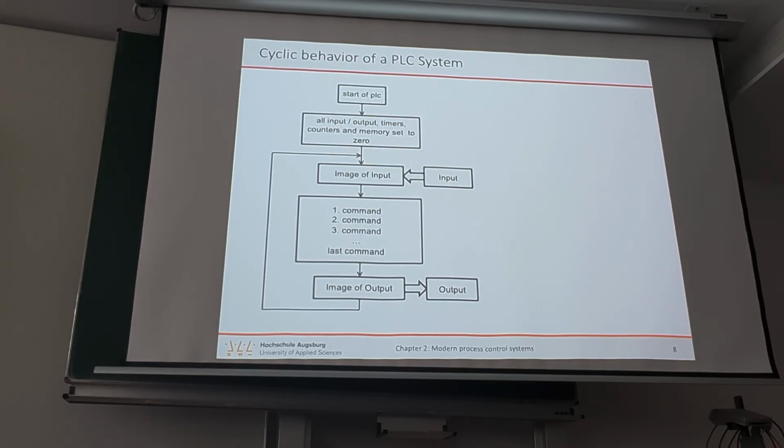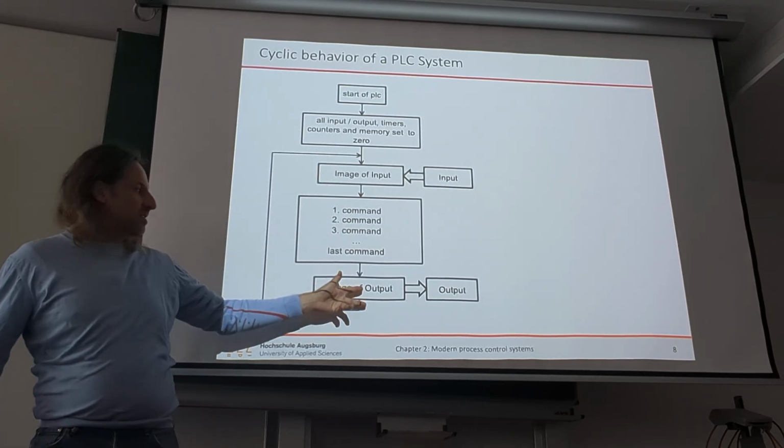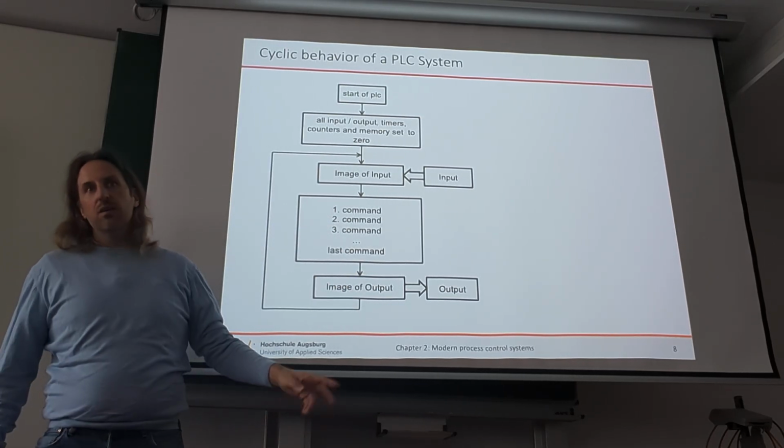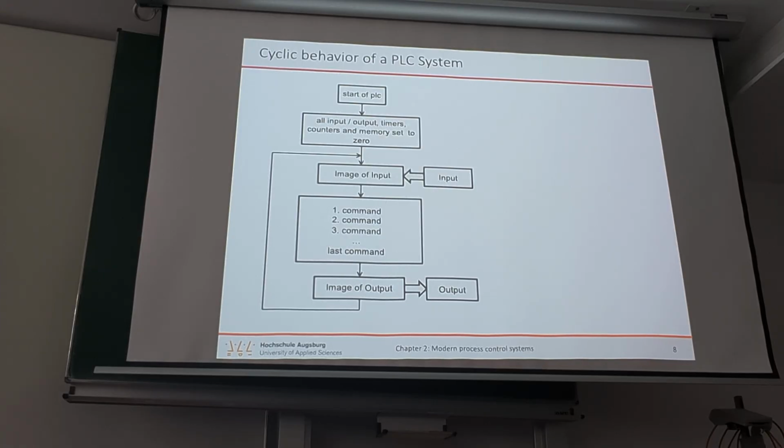And also in control systems, you have dead times in the control loop, and if you can exactly specify the dead time, you can optimize your control strategy. And here you have exact dead times between this input and output, because it's a snapshot in time.